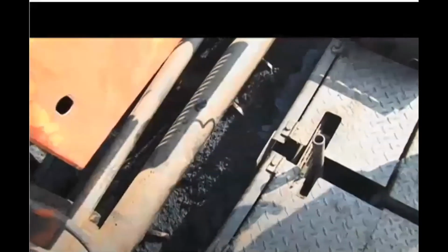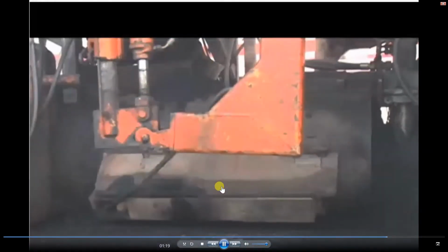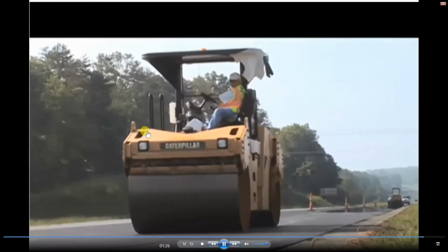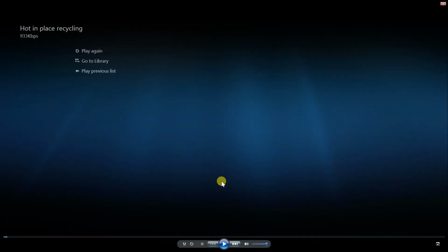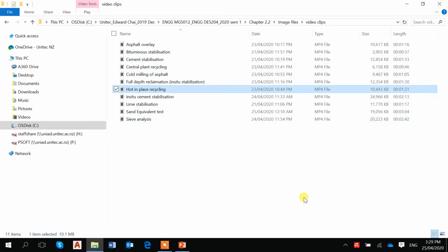Small quantities of additional construction materials may also be added to rejuvenate the asphalt binder in the recycled mix. For this job, a small quantity of polymer-modified asphalt emulsion is sprayed from a separate liquid holding tank on the hot-in-place recycling machine onto the re-engineered pavement mix. The recycled loose mix is finally distributed, leveled, and compacted to target pavement density using mechanical rollers working behind the hot-in-place recycling. Okay, so that is surface recycling of the existing pavement.